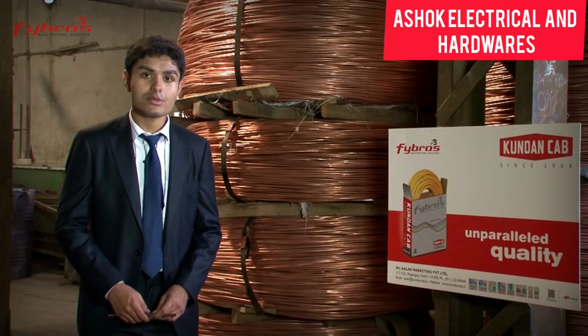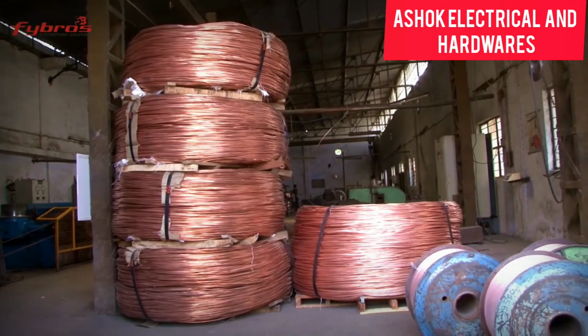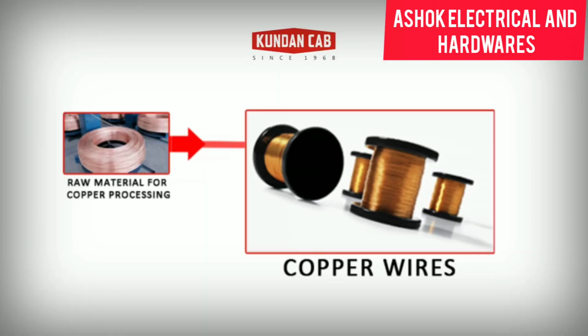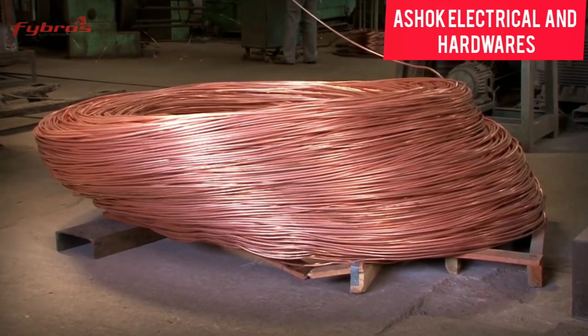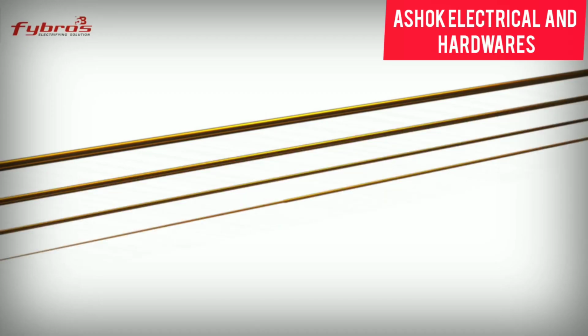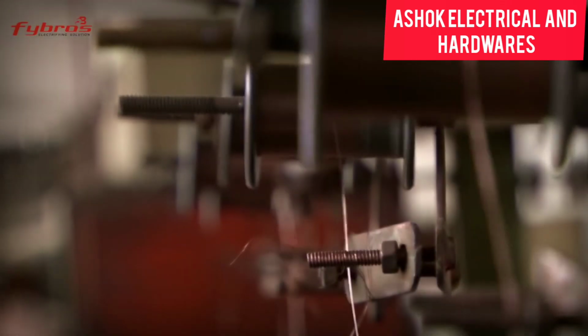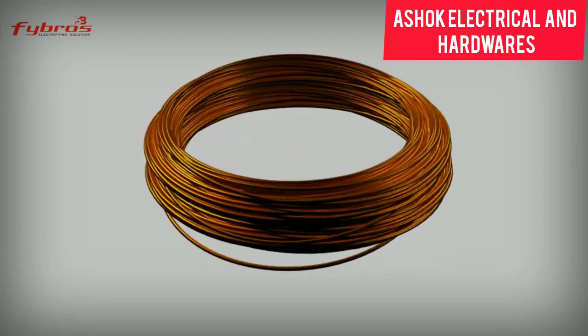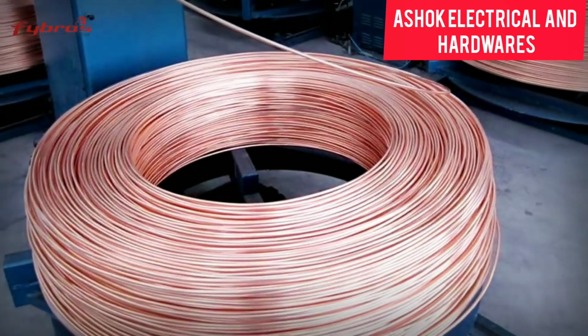The whole process begins with checking the conductivity and purity of the most important raw material, the 8 mm copper rod. Let's have a look at the copper wire manufacturing process. It starts with an 8 mm copper rod drawn. This consists of reducing the diameter of the copper rod gradually to its final diameter to increase its ductility and conductivity. Rod is procured from Hindalco or Sterlite, which is in its purest form.